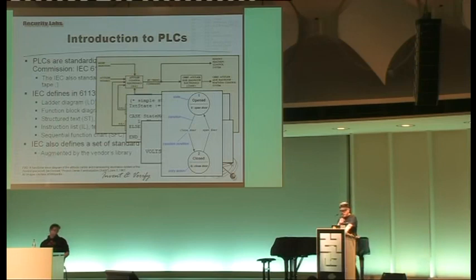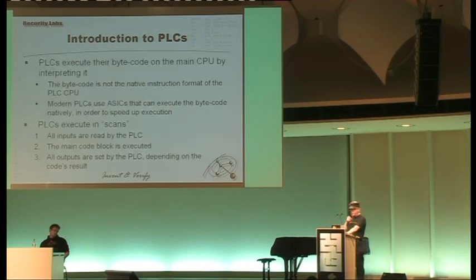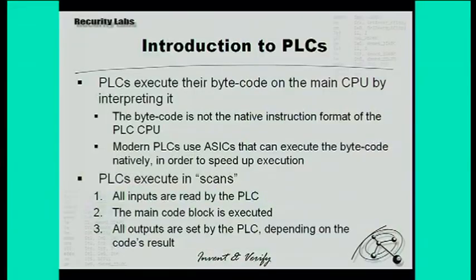The IEC also defines a standard set of libraries. Think of it like your libc. There's just a standard set of instructions, functions. So the PLCs actually don't natively execute the code that you're pushing on them. Most of the older ones that are still in use actually emulate the code, so there's an actual operating system layer, a thin layer on top of the real hardware. The real modern ones now use ASICs that can natively execute this bytecode.